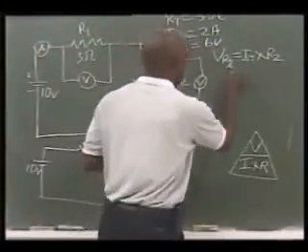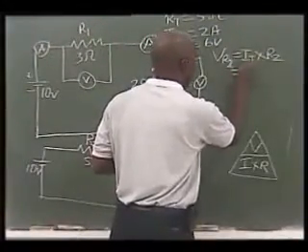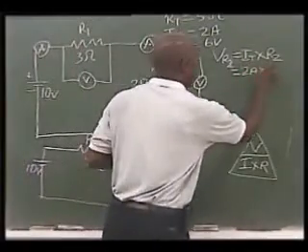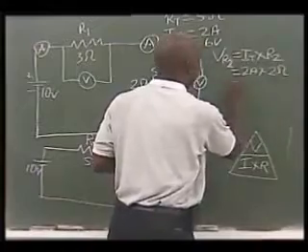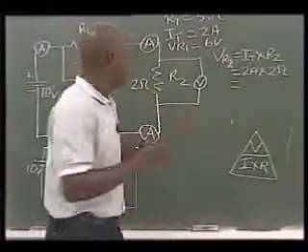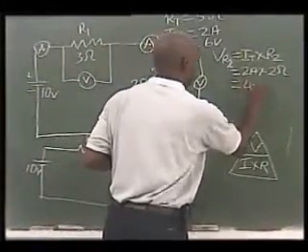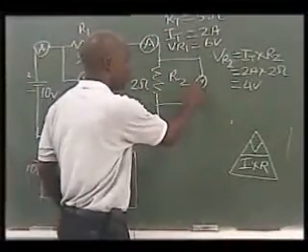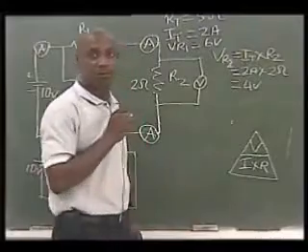And again, we're going to substitute in. We know that IT is 2 amps, multiplied by R2, which is 2 ohms. Okay, 2 2s are 4, gives us a total of 4 volts. So the voltage that this voltmeter is going to read is 4 volts. Okay?